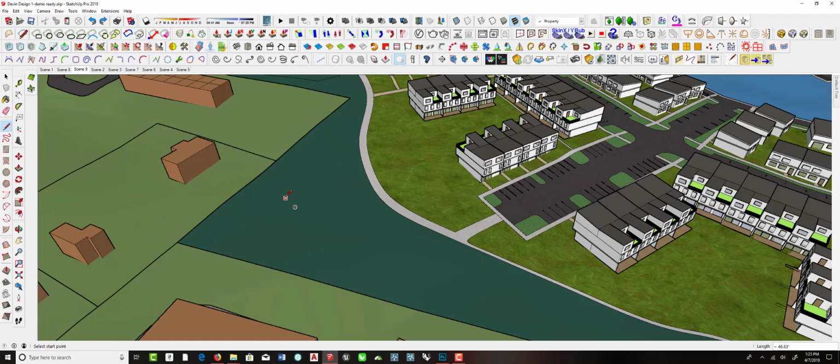Yeah. What I do want to do now is group this. So I'm double clicking, group it. I don't want these lines that I'm drawing to get connected to that in terms of the geometry. So I don't care if they cut through it. There we go. Now you can see it's not trying to stop the line tool because it's not actually connecting to any geometry within that group. Okay, so there we go.